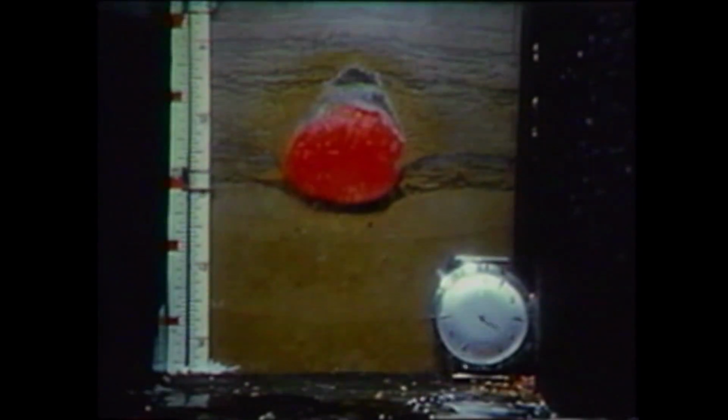Now, the smaller dowel begins to lift. The void beneath the larger dowel fills with water. That softens the walls so they collapse inward. Other objects embedded in the soil can also be lifted. For example, in this experiment, an artificially colored rock was lifted 3 inches by frost action.